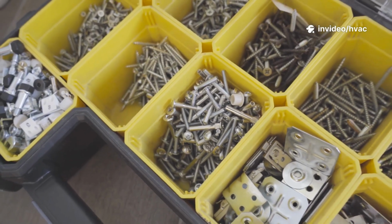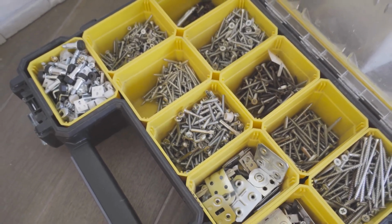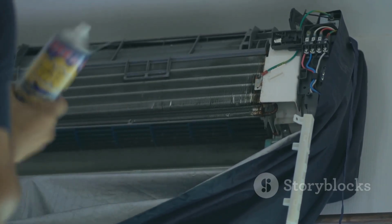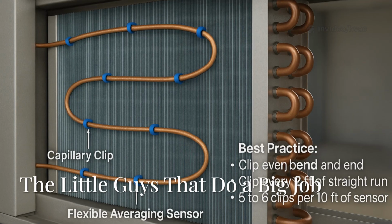For a 4-pass coil, that usually means at least 10 to 12 clips per sensor depending on the coil size and sensor length. Even the little things matter. Organize your hardware before starting to avoid delays during installation. Proper use of these clips ensures your averaging sensor stays in place for years to come.